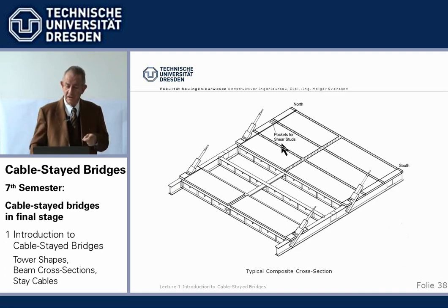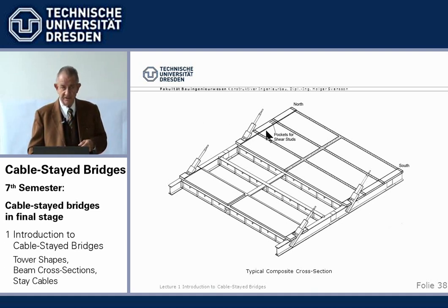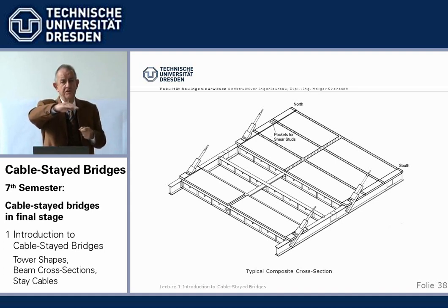So, in longitudinal direction we are compressed by the inclined cables, and in transverse direction, if we use two cable planes, then the beam in between the cable planes acts like a simply supported beam with a bending moment which causes the concrete, as top flange of the cross girders, to be in compression.